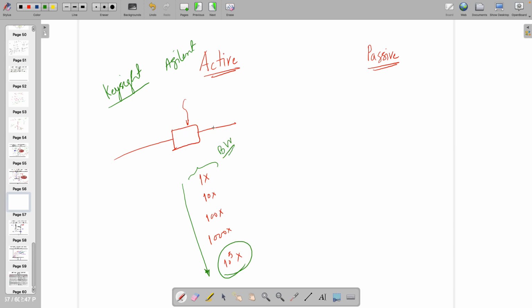Look, these probes can work at very high frequency. If you have seen, SMA connectors are there. There is also BNC. BNC works easily with gigahertz, right? 1 or 2 gigahertz, no problem. SMA is much higher than that. SMA, SMB, SMC, the sub miniature, which is golden colored.